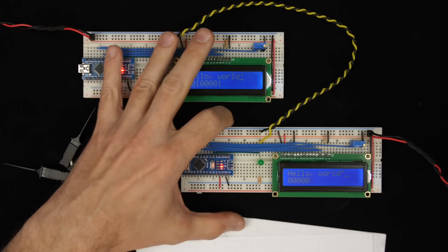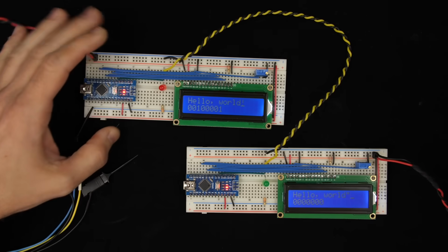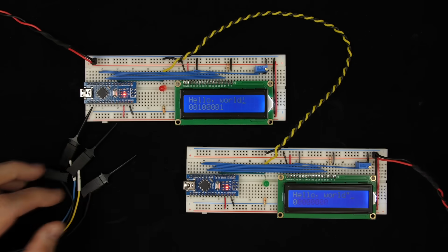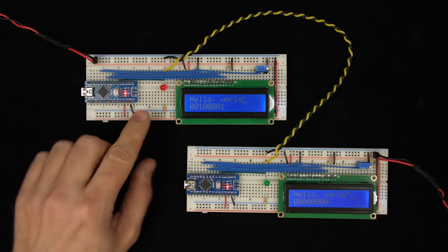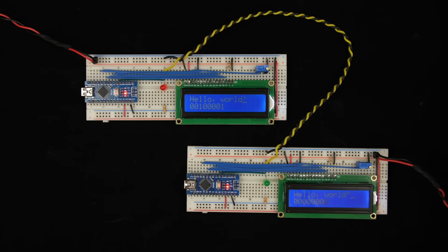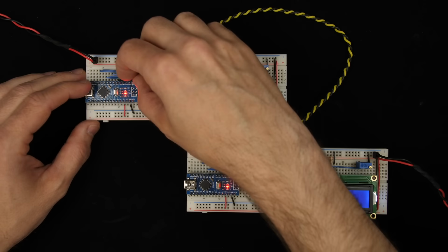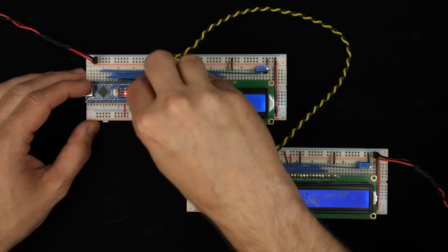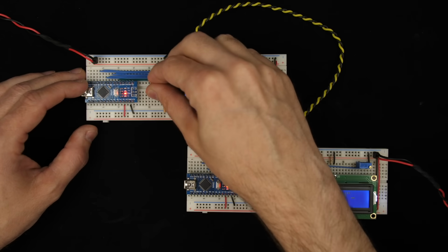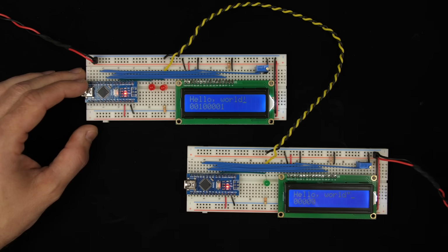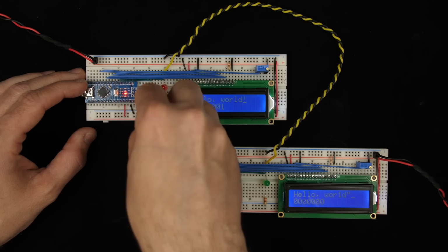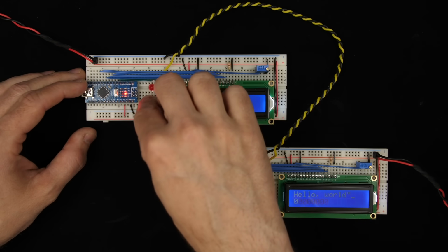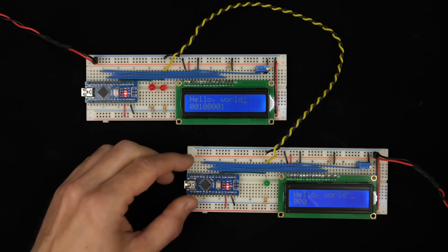So for the clock signal, that's just going to be another pin coming off our Arduino here. So let's see, if we're using pin 3 for our data, then we're using pin 4, 5, 6, 7, 8 for the LCD. And let's use pin 2 for the clock. And I'll just hook that up to another LED over here, because this is just going to be a second signal that we're going to send across from our transmitter to our receiver. And just like before, I'll connect that LED to ground through a current limiting resistor. Again, that's a 330 ohm resistor.